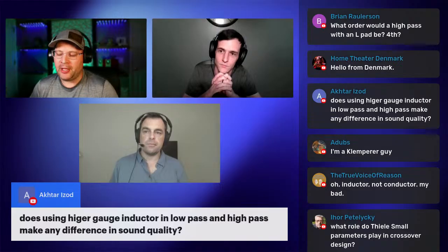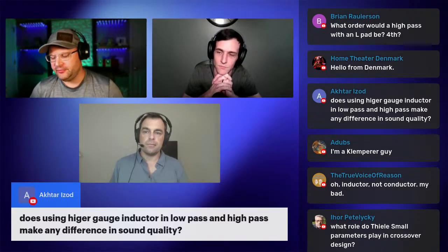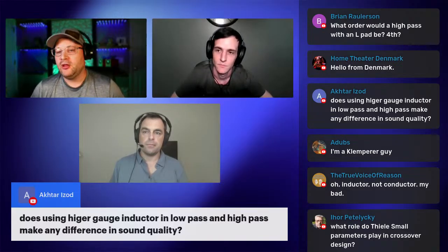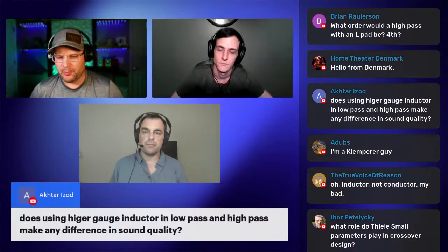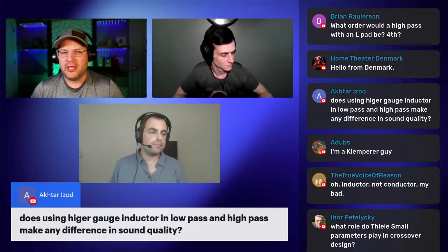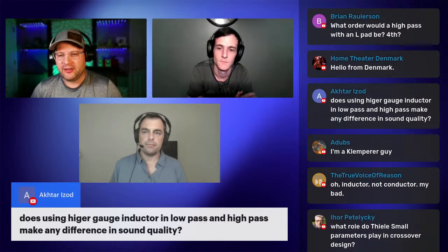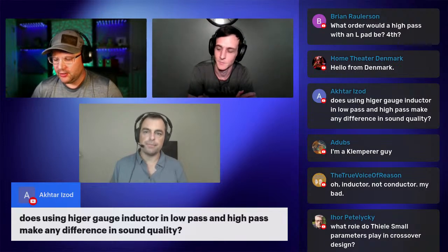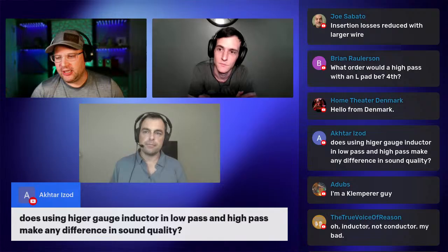Another reason, by the way, if you're wondering what the resistance of your inductor is, go to a page like Parts Express or wherever you're buying your crossover components from and look for DCR. That's going to stand for the DC resistance. And that's going to give you that answer.